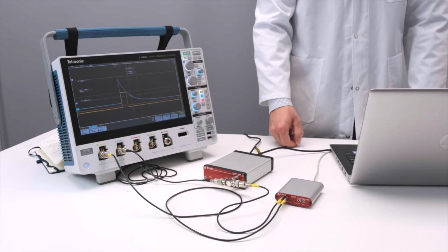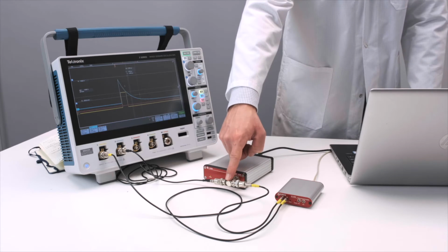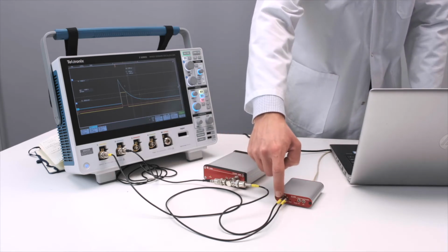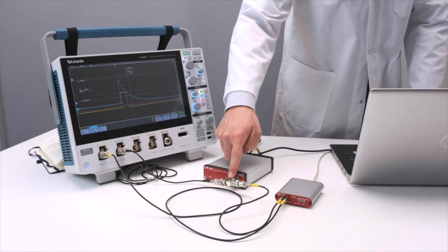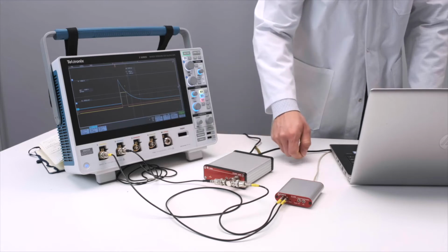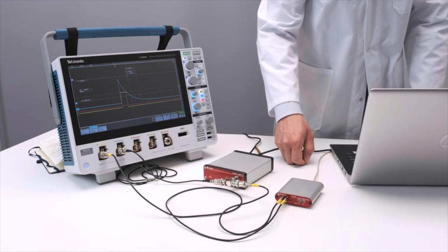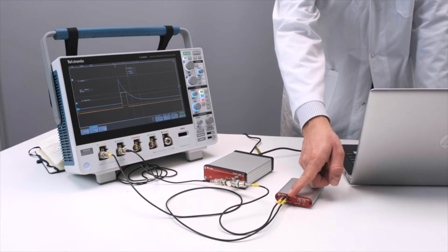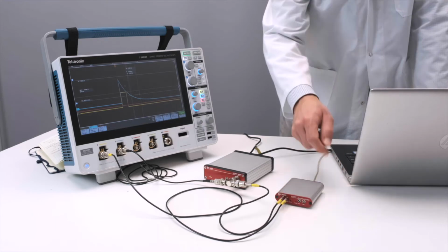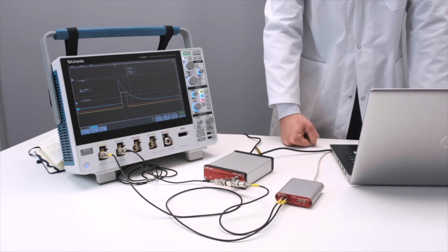The emulator generates an analog signal that is provided to the CDK board and also to the oscilloscope using this split T. And in the board we will acquire the signal using the ADC. We will compare the signal with a fixed hard-coded threshold, and we will drive the LEMO output in order to be high when the signal is over the threshold.